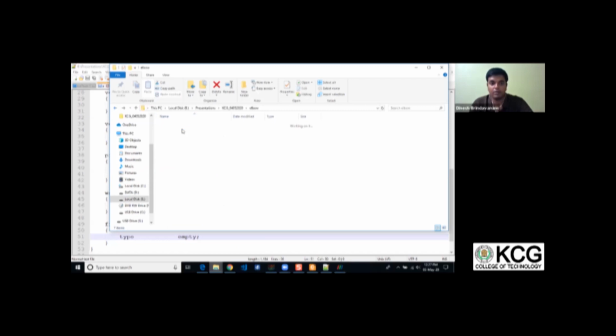Next I'm going to show constant. Constant has transport properties. These are not going to be very important at the moment. Now this is the important part. In this one you see there is a file called CONTROLDICT. You leave these two parts alone. These are the things I extra added to do the parallel simulation. This part is for parallel simulation, this one is not required.